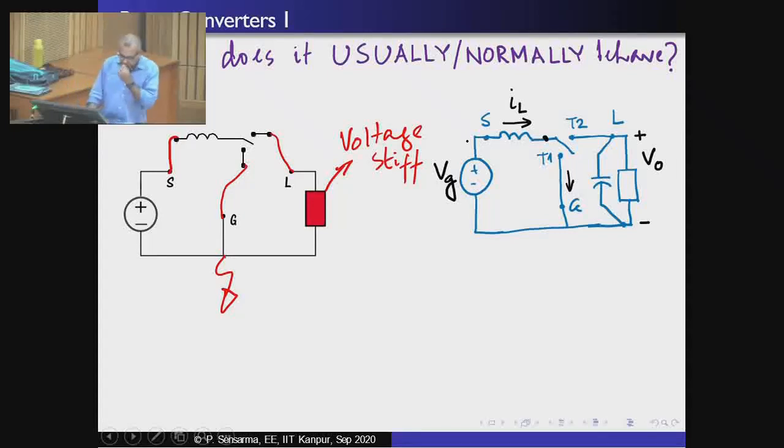For the voltage source, it is given, and the reference current direction in the inductor is also shown. For the inductor, the reference voltage polarities are also shown. See that the voltage polarity for the inductor and the reference current direction in the inductor conform to what is called the load convention, and we will use this load convention right through the circuit for indicating the reference voltage polarities and reference current directions through any circuit element.